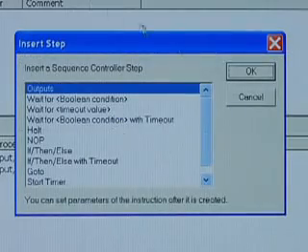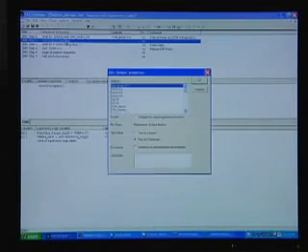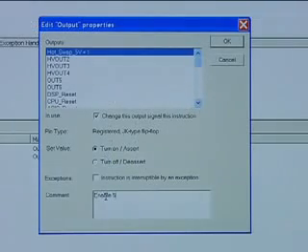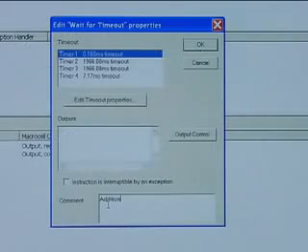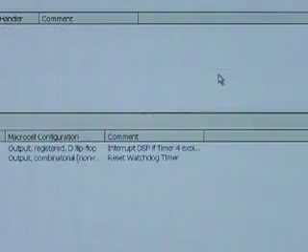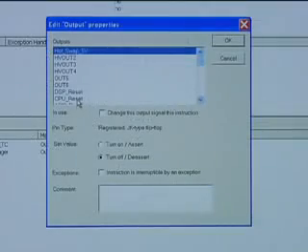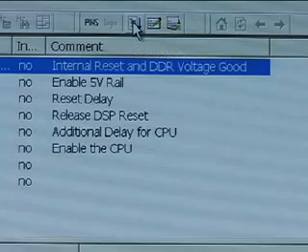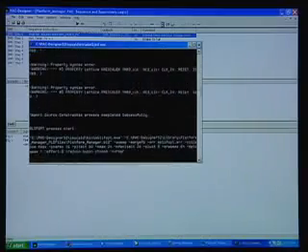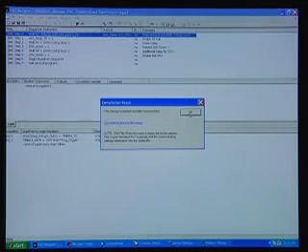Now that we've configured the I/O and timers, we can define logic sequences for supply sequencing or reset distribution using Pack Designer's LogiBuilder tool. LogiBuilder offers an easy-to-use method for the creation of simple sequences and combinatorial control functions. In complex systems, coding can be accomplished in HDL or Verilog. Pack Designer enables you to import complex HDL logic modules and implement them in the FPGA fabric alongside simple LogiBuilder CPLD code. After defining sequences for both the CPLD and FPGA sections of the Platform Manager, the entire design needs to be compiled and downloaded.